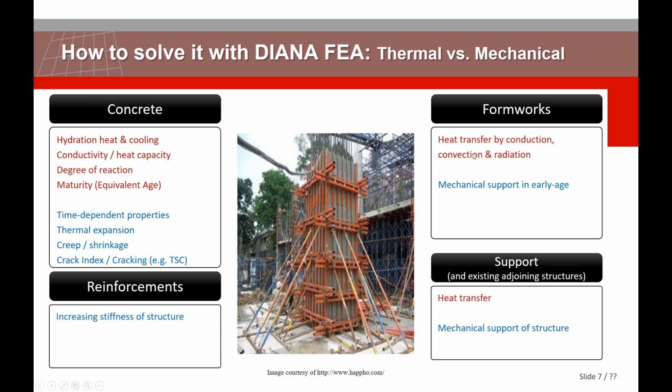And formwork has two aspects. Heat will be transferred by conduction, convection, and radiation through the formwork, and the formwork also works as mechanical support until you remove it. And we have support. Normally you have heat transfer from your concrete to, let's say, the foundation, and the heat will go through this foundation.